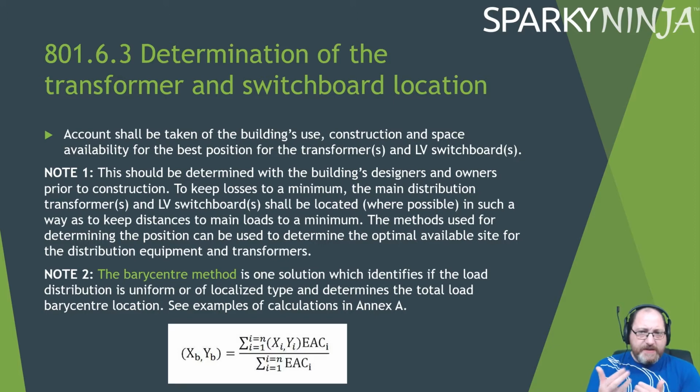You can Google what barycenter is about, but it's all about something spinning around the center point. We want to have our intake in the middle so that the distribution circuits go out to the same length. If we had the distribution on the corner, then the distribution to the furthest corner would be long and there'd be losses. So we want to have our distribution in the center as best as we can.